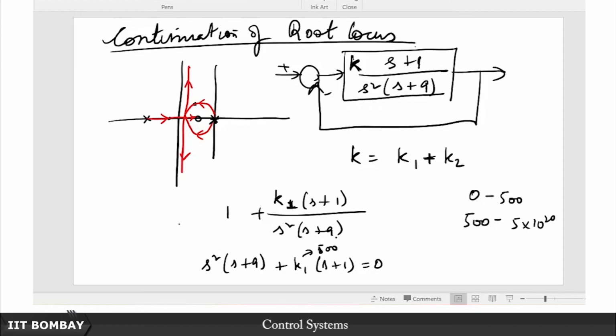So now, if I am just interested in how the roots vary, or how the closed loop poles vary as K2 is varied from 0, so the K2 = 0 setting is actually the 500 setting of K1, but I am only interested in when K2 is turned on from that instant onwards, alright. So then for me, who is interested in studying the variation of K2, I might as well, instead of treating this original plant, I might as well treat this,